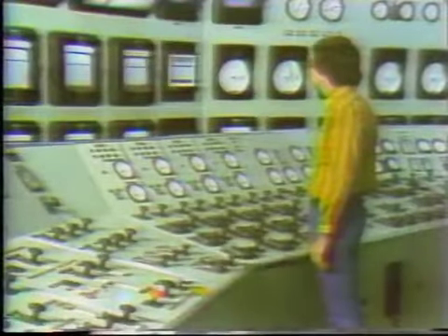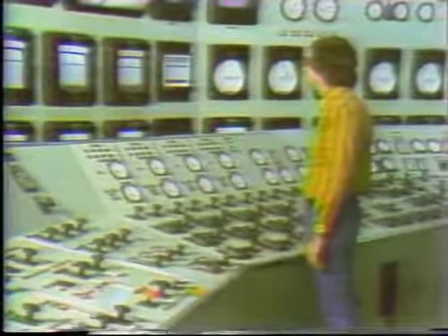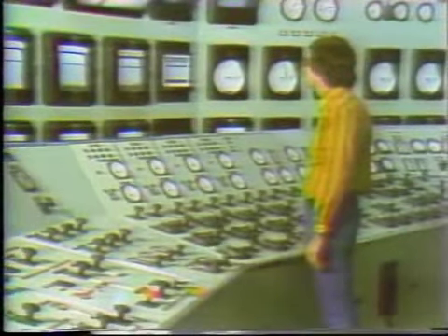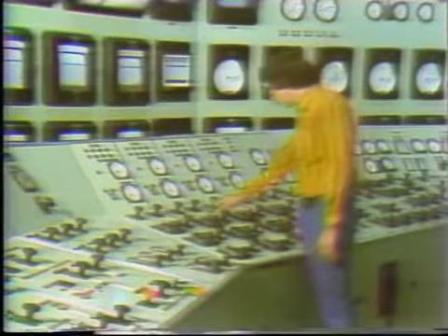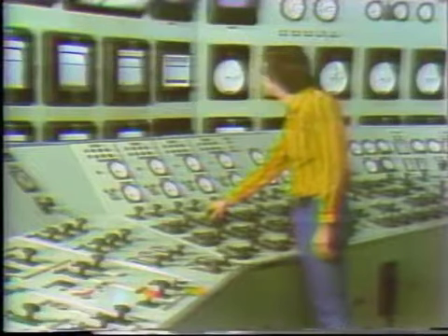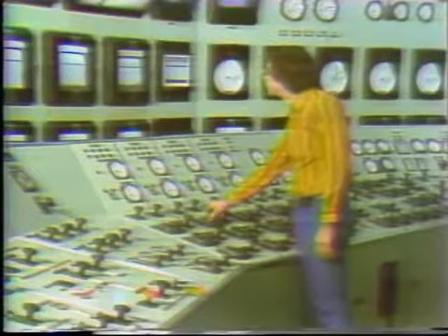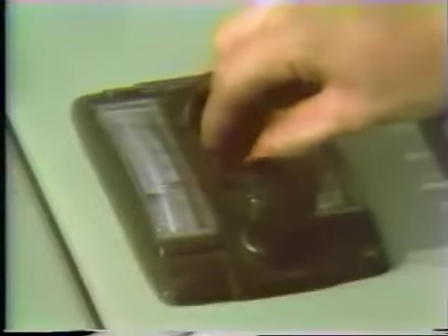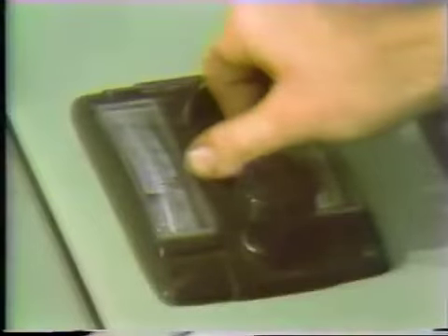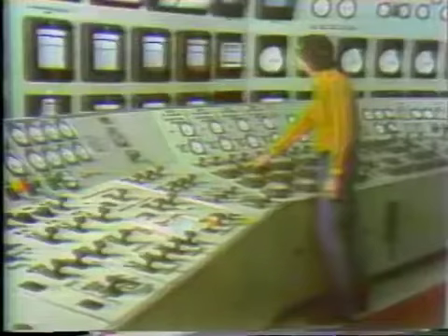Now, while all of this is going on, the operator is making routine checks of the flow rates and comparing them to what he has seen under the same conditions before. Should he spot what he considers a potential problem, for example, the combustion airflow rate may be too low, he may have to make adjustments to an automatic control system. In most cases, this will restore the unit to normal operating conditions.